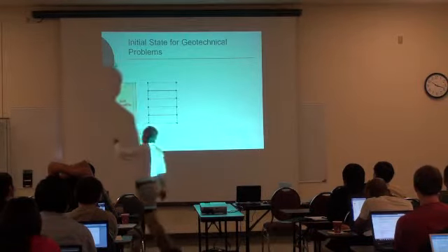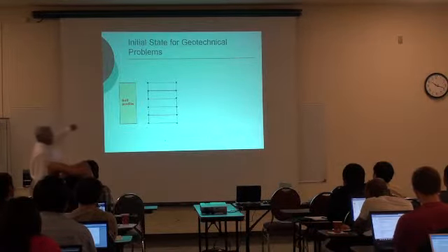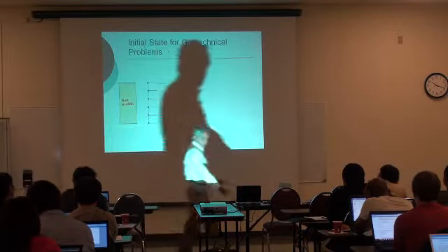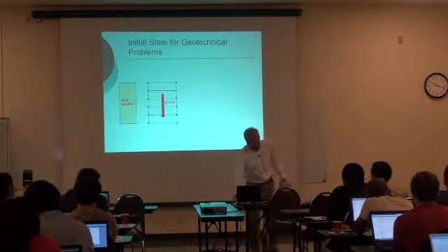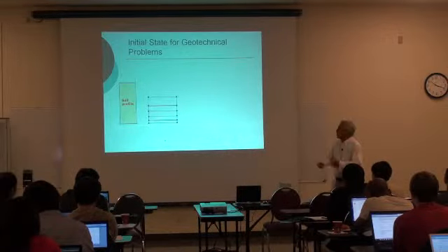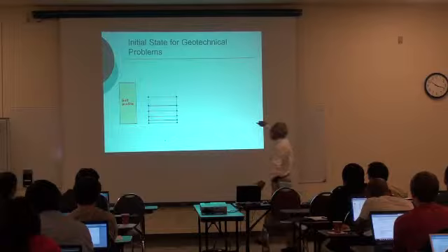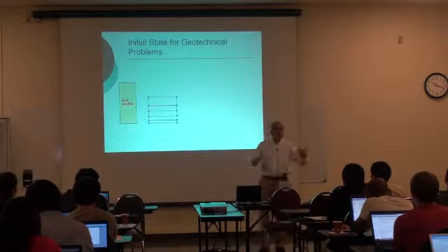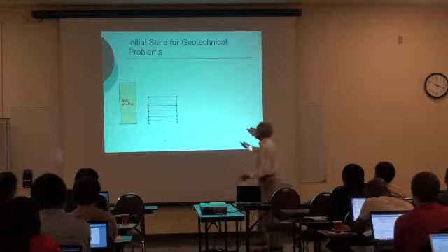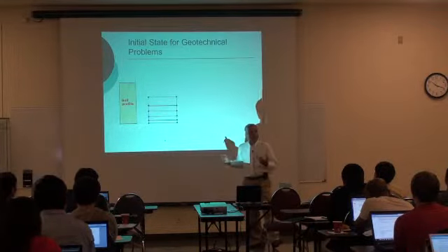The other thing that we have implemented is the idea of an initial state. When you have a soil profile, you model the soil profile with your elements. And when you apply gravity, what happens? Immediately you will have a deformation. But that deformation doesn't exist in nature. So when you continue your analysis, you will continue with an initial deformation that is not really there. And that can create problems when you try to connect this to a pile or where you have contact elements.